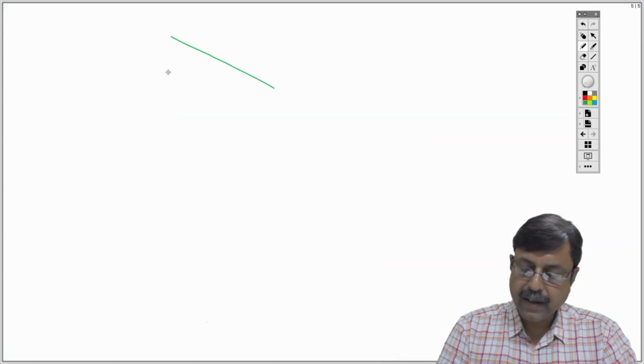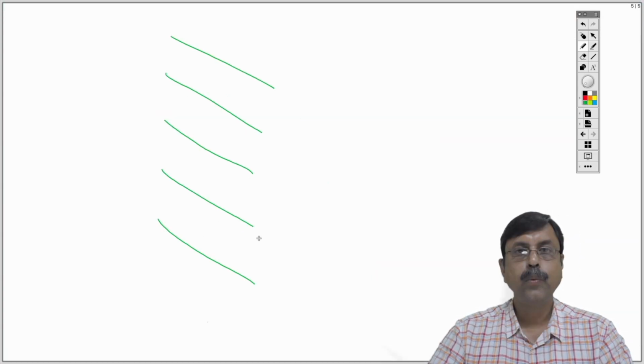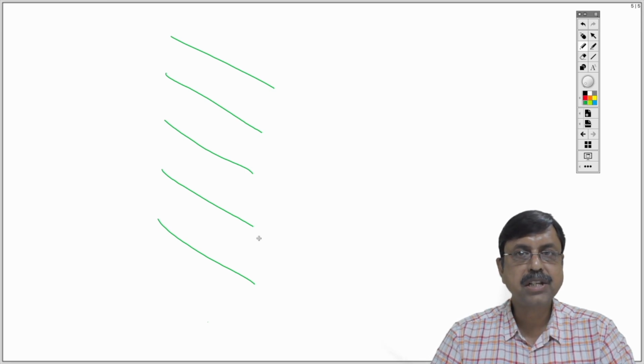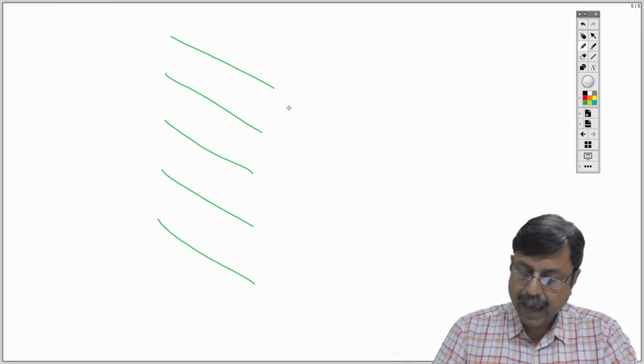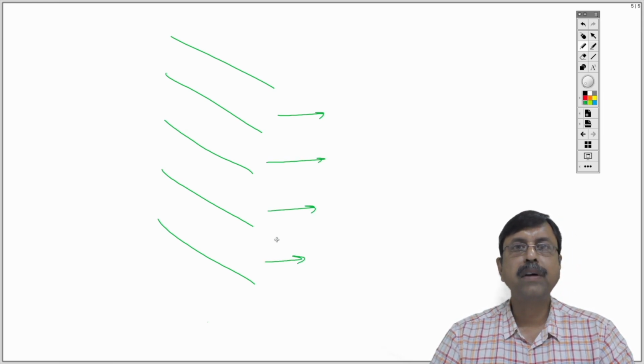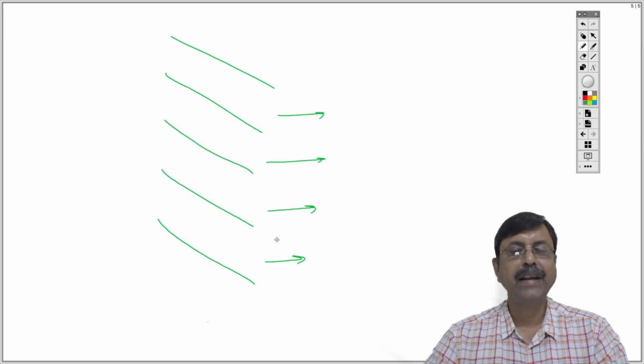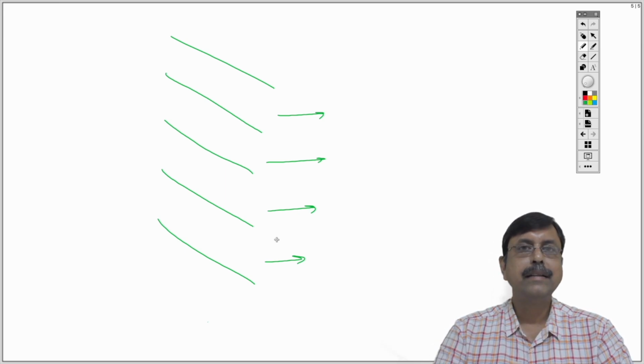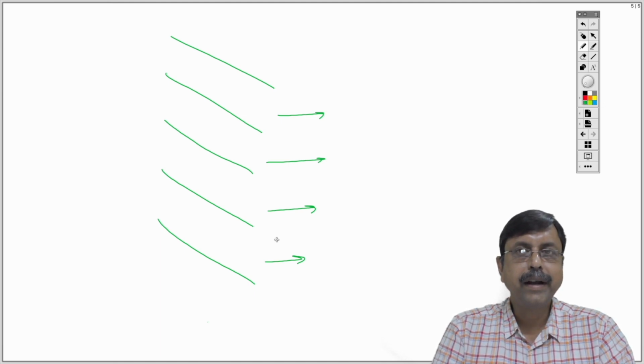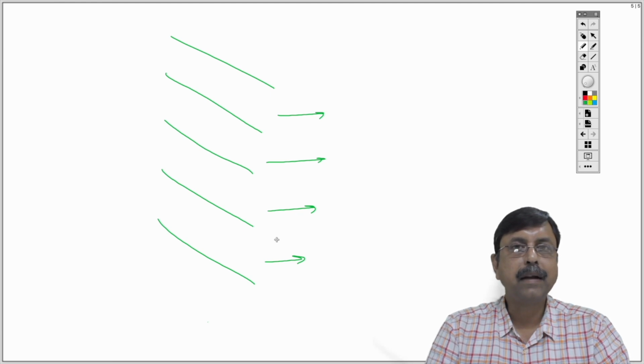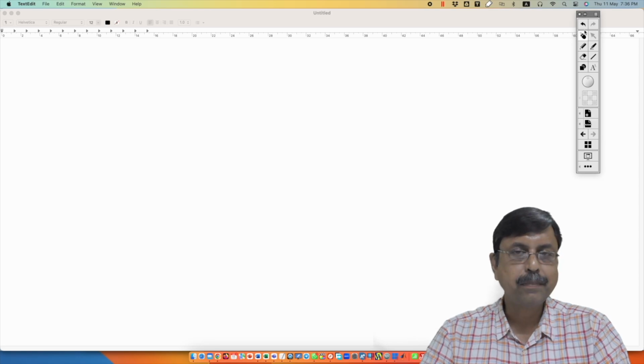Now, if we have a series of such screens with decreasing order of mesh size, then we will have several of such overflows, and those overflows will be separated and segregated based on certain ranges of particle sizes. That is the working principle of a screening device. It separates and segregates solid particles as per their size ranges. Now let us go to the Aspen Plus simulation window to learn it better.